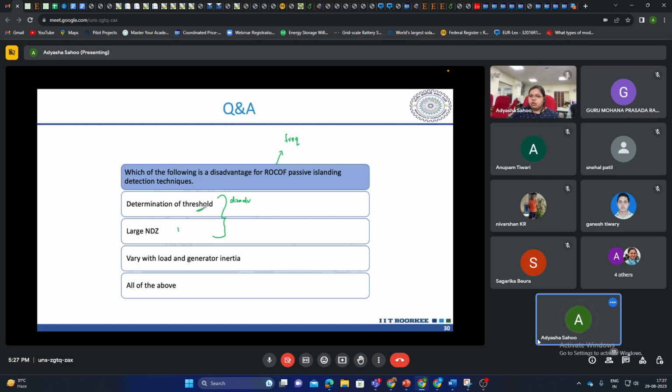So this threshold is very crucial. The selection of this threshold will determine if it is in the detection zone or not. Let's say we have a threshold of 5, it is very crucial because just within this short range, we may get islanding detection or not.